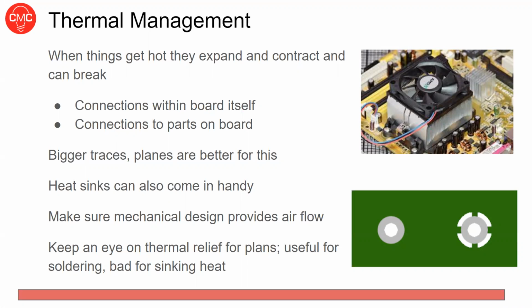For certain ICs, like switching regulators or ICs doing computation like a computer, you can also just throw a heatsink on there. These are really good tools for dissipating heat, and then fans if necessary, depending on how hot these things get. If you're working with mechanical engineers, or doing the mechanical design yourself, you can consider airflow in whatever system you're putting this in. So if you're mounting this inside of a chassis, maybe ensure that there's some airflow throughout the system.